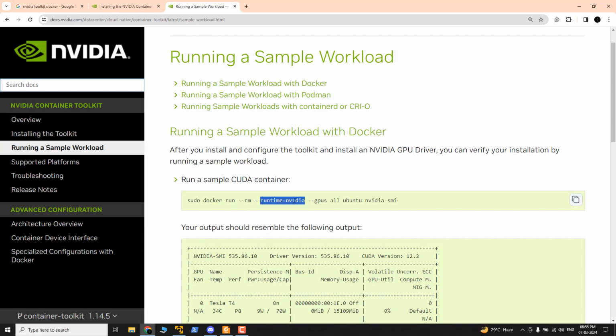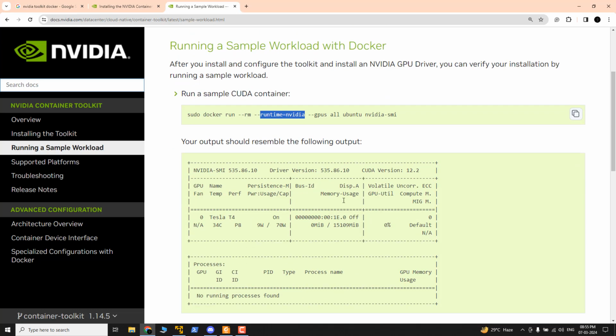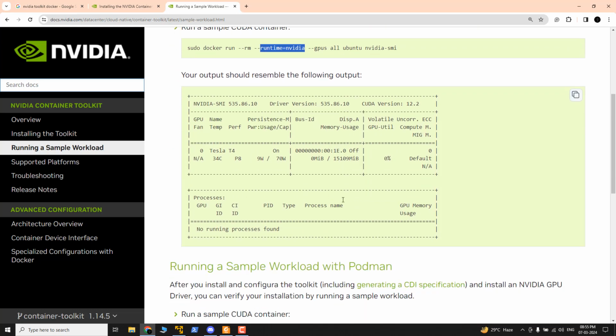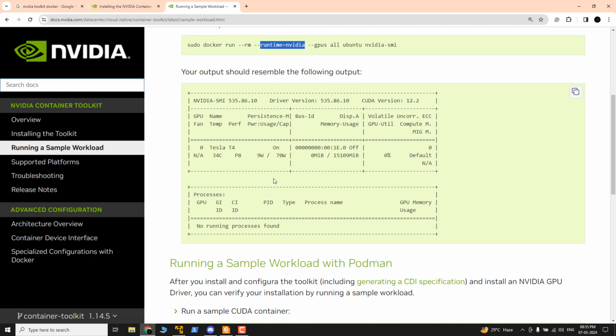Then we can make sure the NVIDIA graphics card acceleration is available in the Docker, which is very important because if you are doing some training or working with extensive simulation in Gazebo, graphics acceleration is very important.